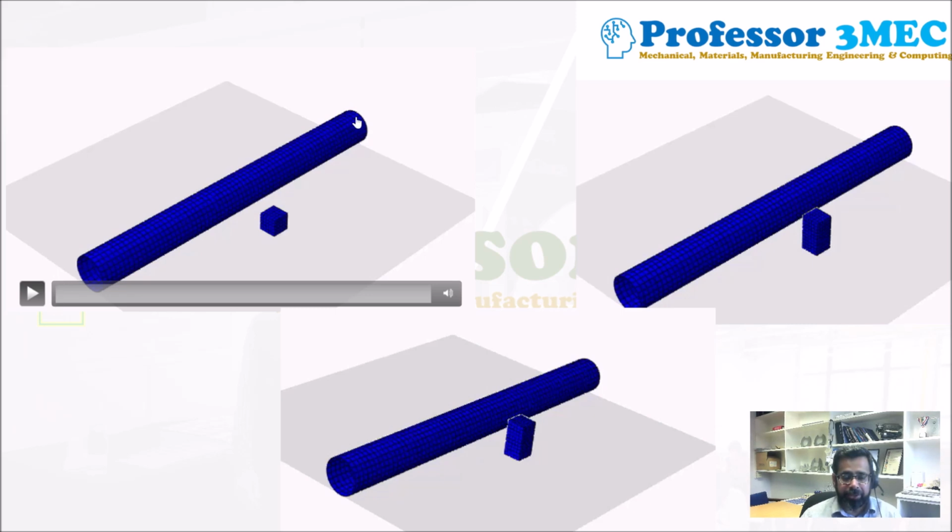Pipeline will be modeled as a shell. Fish trawl, in this case, is cubic, but you can use whatever shape you have. And this gray area is the soil part, which in this case we are modeling as rigid, but if you know the friction coefficient, cohesive properties, angles, etc., you can use those as well.